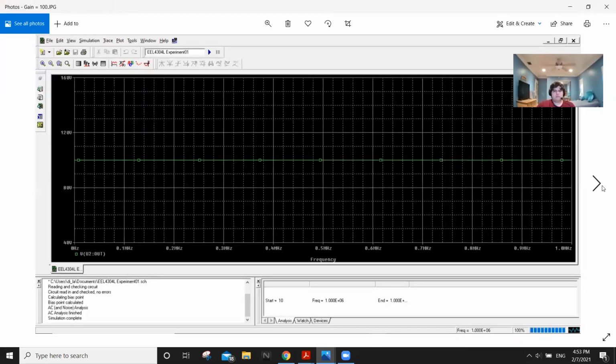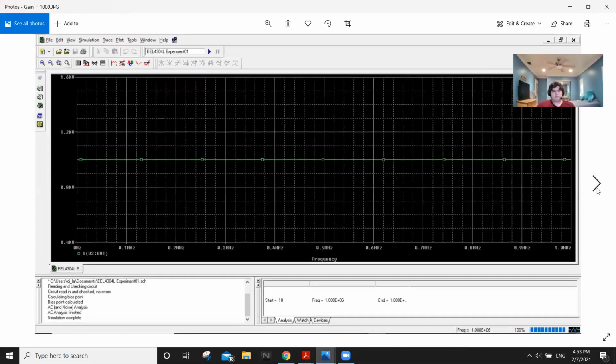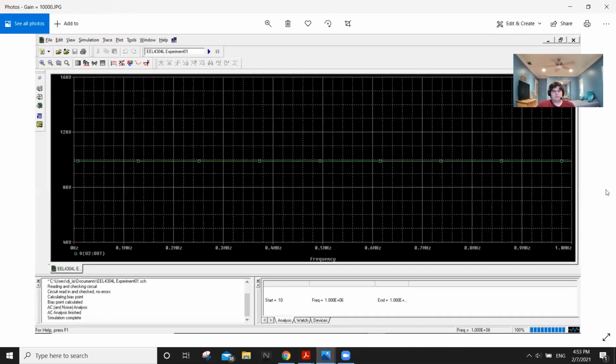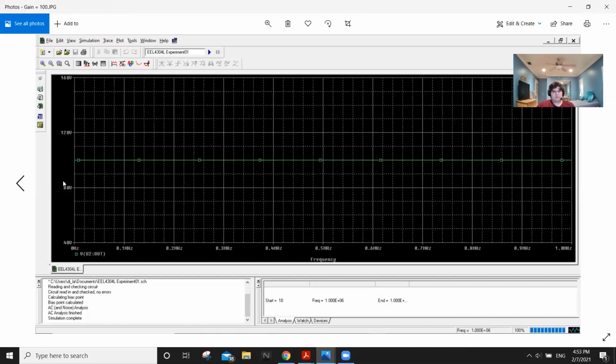And then changing this quotient of resistances, we can get different values of gains. So here we have 100 gain, 1,000 gain, and 10,000 gain, which was the implementation limitation because we don't have higher resistances. Since it is only a resistance quotient, it's not related to frequency, so it's going to be a constant gain throughout the whole frequency range.